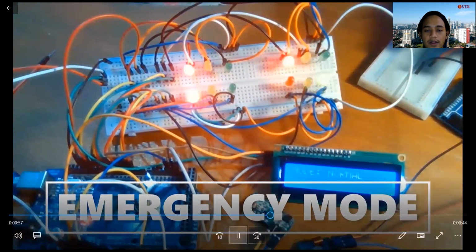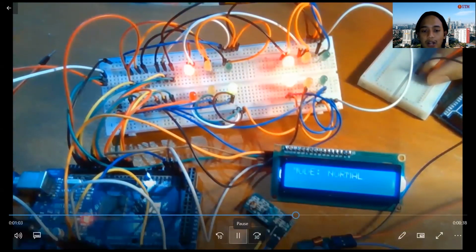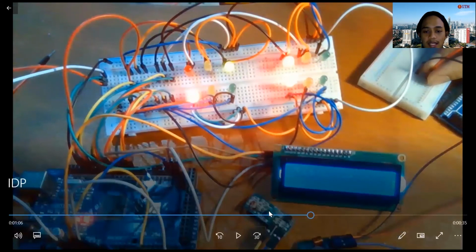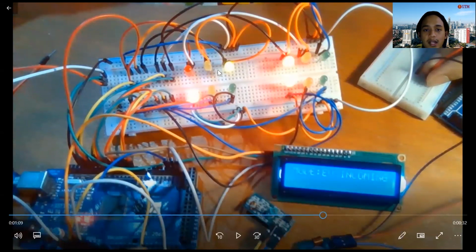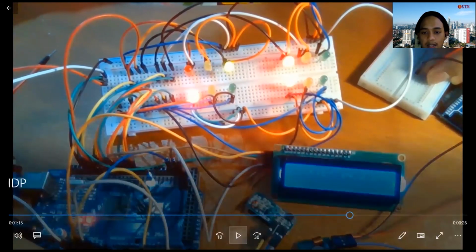So for the emergency vehicle mode, the device that we're going to use is this transmitter and receiver, as I explained before. So when I complete the circuit, meaning that I turn on this transmitter, the transmitter will send a signal to this receiver, and when the receiver receives that signal, it will turn into emergency vehicle mode. Since this transmitter is connected to this set of traffic lights, assume that there's an emergency vehicle on this traffic light link. So it will maintain a green light until I disconnect the transmitter again.